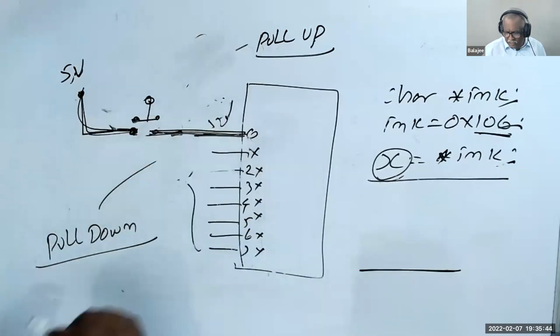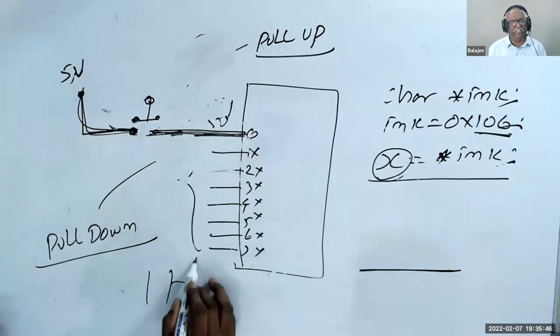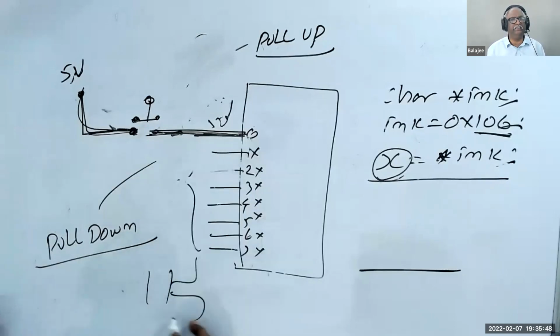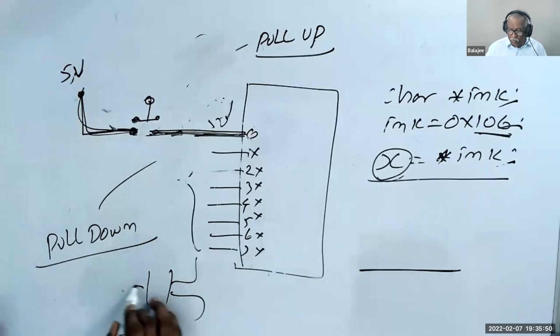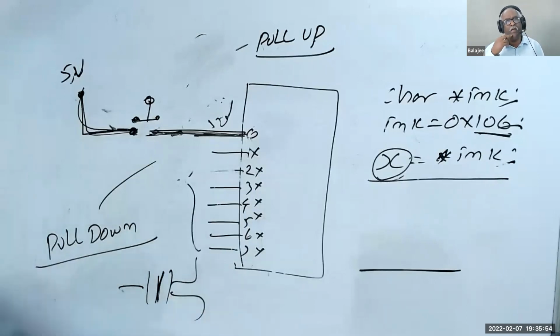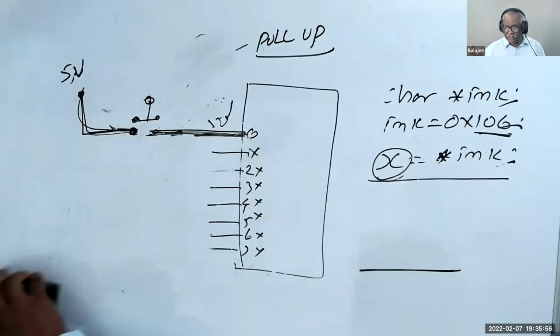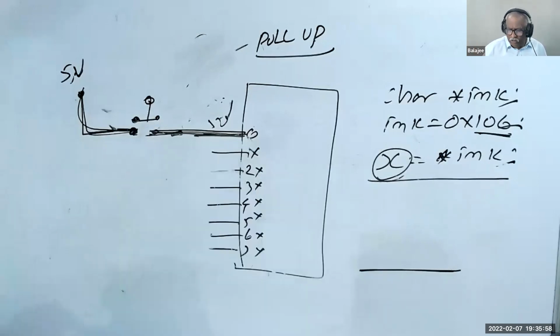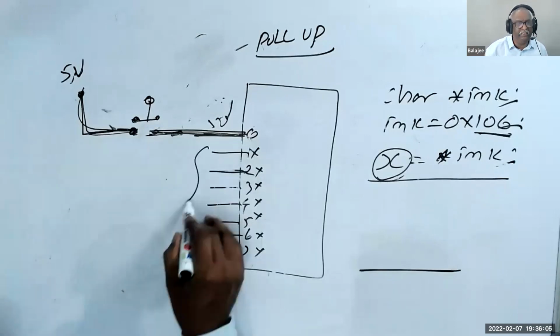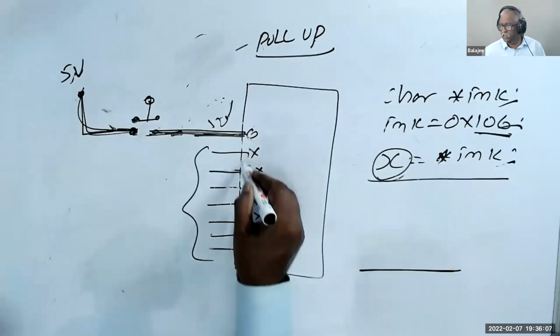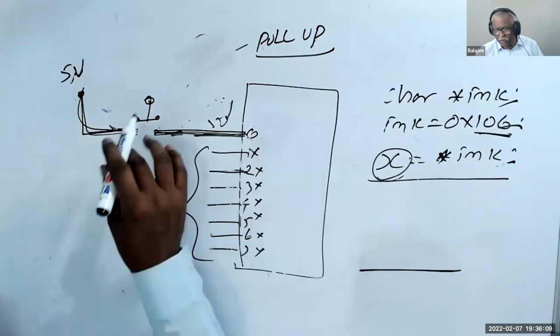It's because the input is nothing but a capacitor. You have to understand that. Please understand, you should never leave a pin open. Now, in our connection, I left all the other pins open. Here there are 7 pins. The X, that means that when you don't press the switch, if you read it, you will get this bit as 0 because you connected to ground.